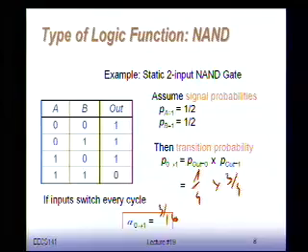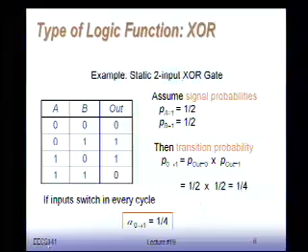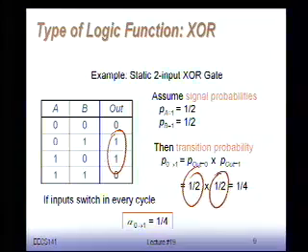Now think about an XOR. If you think about an XOR, you see that the probability of a 1 and a 0 is equal. If you look at the output, there are two versions that have 0, two versions that have 1. So the probability of having a 0 is 1/2, and the probability of a 1 is 1/2. So the product of the two is 1/4, which is equal to 4/16. So it's a little bit higher than what an AND gate is.